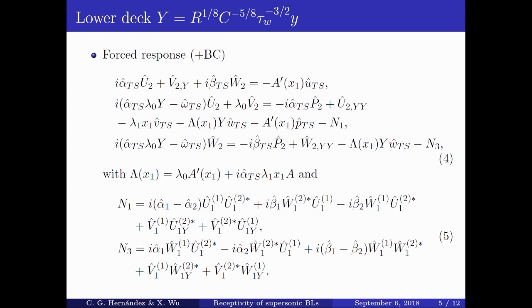So in the asymptotic expansion, we have three different kinds of terms. The leading order terms are the sound wave. Then there are the terms for the TS wave, which is the eigensolution of the equations, and then the forced response with the subscript 2. For the sound-roughness problem, we will have another extra term which accounts for the mean flow distortion by the wall roughness.